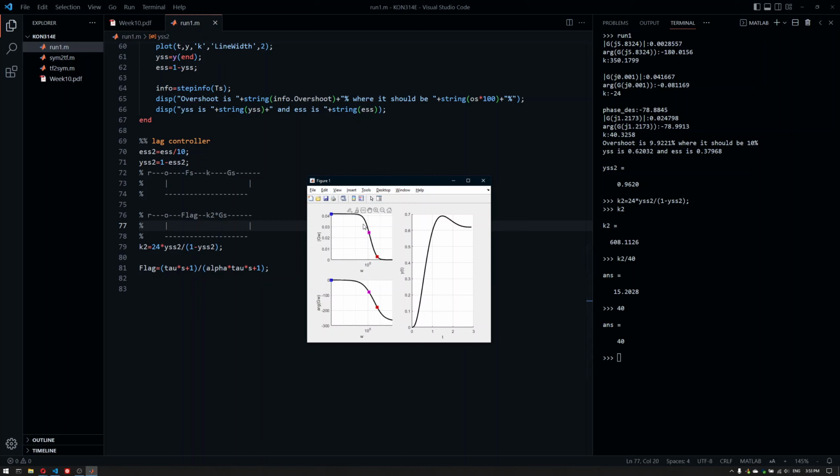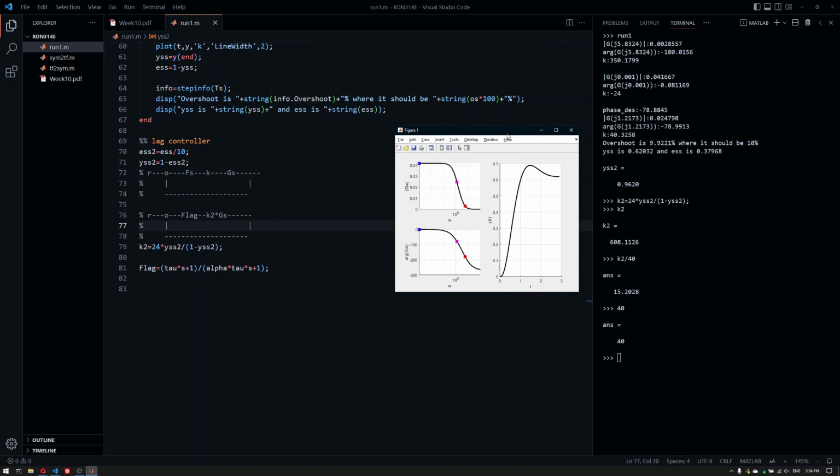If you're searching for something on the plot, you should first divide by K2 and then search on GS. So in the exam, sometimes this question might pop up and you might have only the Bode plot of GS. So you have to calculate or just predict your own gain plot or update the values of your gain plot and read from just one Bode plot throughout the whole question. So be aware of that. That is something that sometimes the exam questions have.